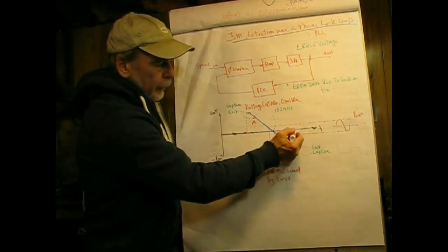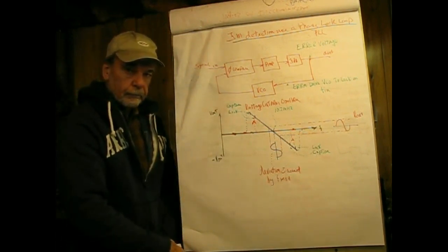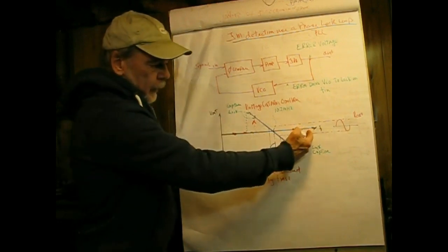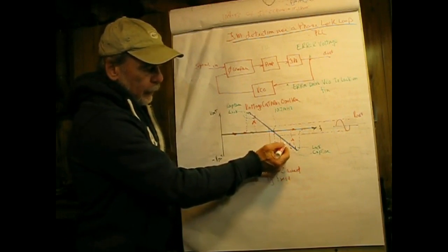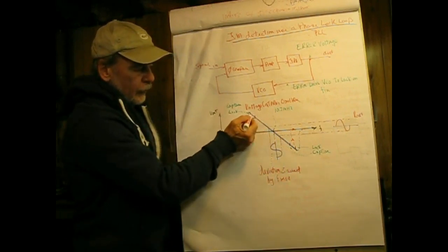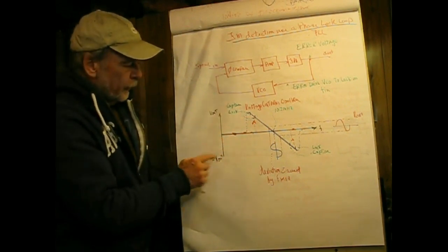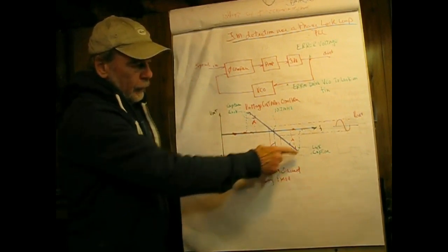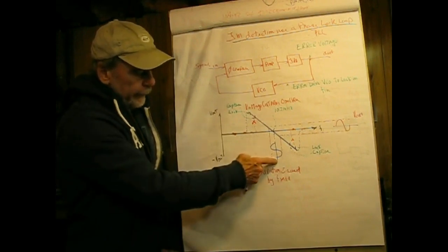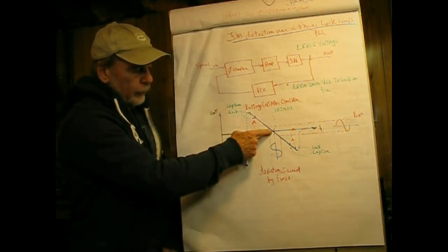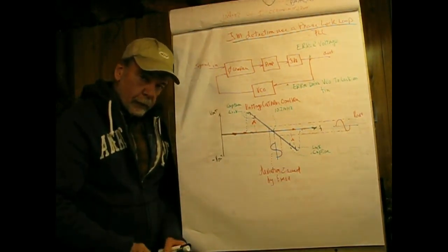And then when I get up here, continuing to increase the frequency doesn't produce any other useful results. Decreasing the frequency, coming back, it'll lock at this point. So I would have a line coming down here, it would follow up the curve to this point, break lock, come back over here. So this is going to be the voltage output, and this is going to be the frequency input. Now what I've done is I've located our intermediate frequency directly here, and that should be the frequency at which the VCO free runs.